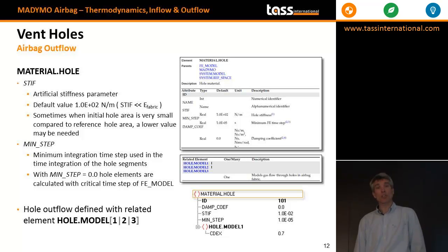And maybe the energy is not even available, and then you can end up in something what we call necking. For that, it's generally better to define a value of 1e minus 2. In those cases you will probably have no necking. It's simple to check by looking at your animations. The min step is something to do with mass.